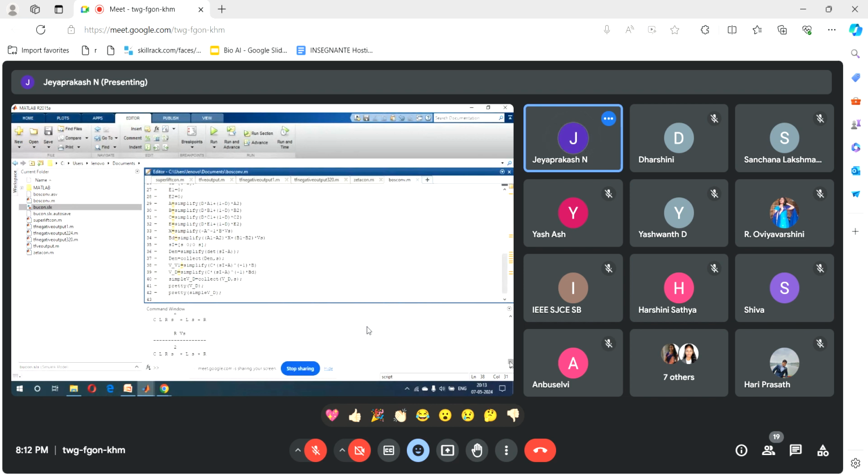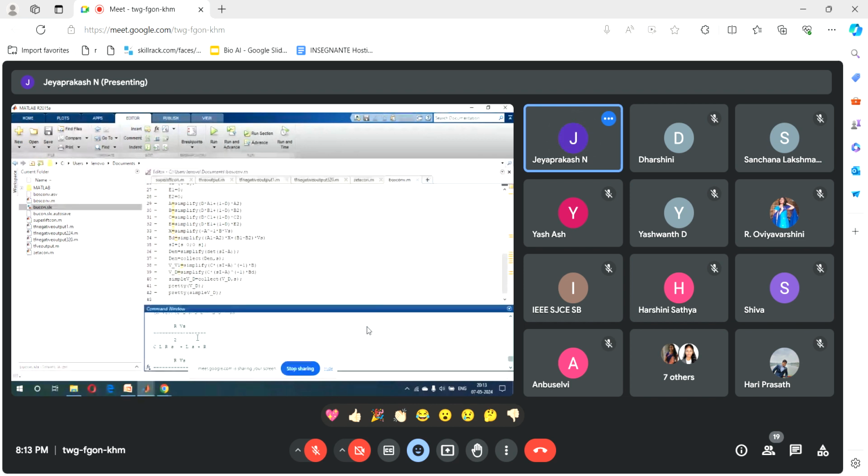And this is one more transfer function. So V underscore V1 is nothing but the output versus input voltage transfer function. The next line, underscore D, indicates the output versus duty cycle transfer function. Now you can look into this transfer function. I am considering only the output versus duty cycle transfer function, and I am going to keep the input voltage constant.